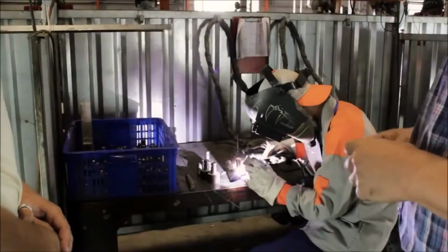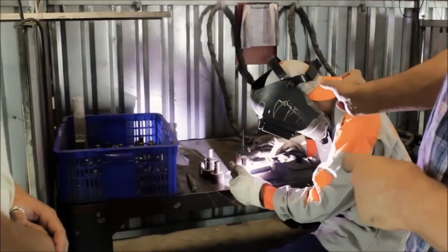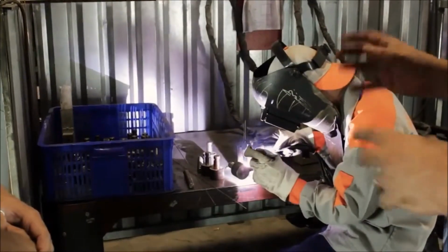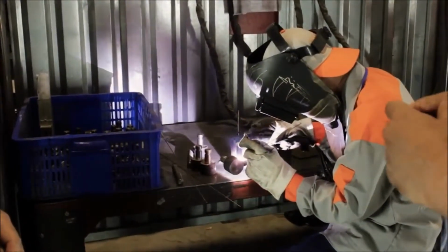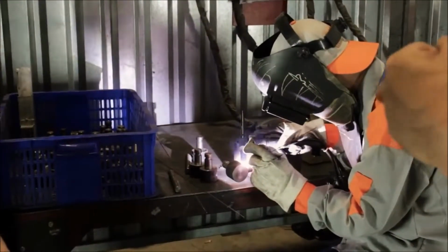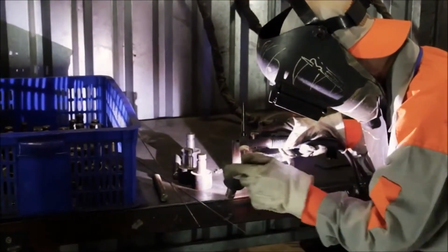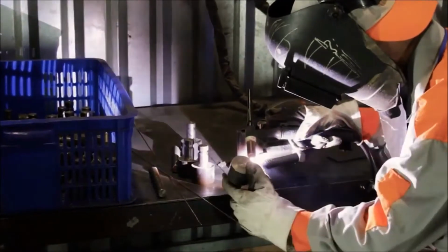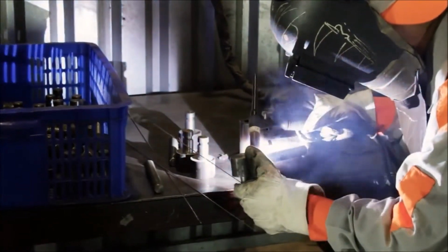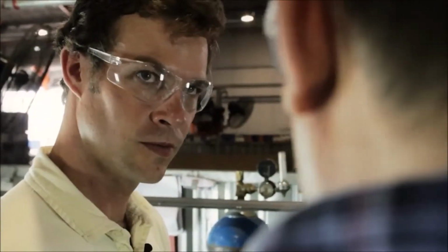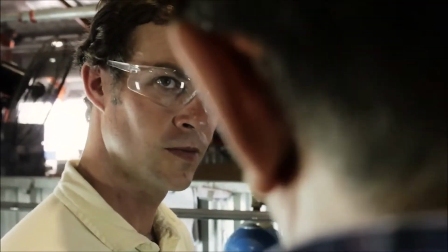So as you can see here, this is where they're assembling the hinge part. That's the hinge head and the threaded round bar that goes into the hinge. The welding process that we use for this particular part is the TIG welding process. After they're fully assembled, the parts of the hinge will go to get electrozinc plated, and then they're powder coated prior to packing.